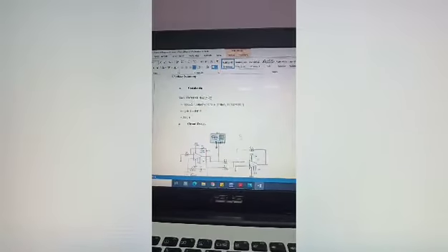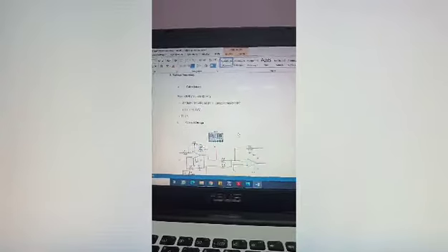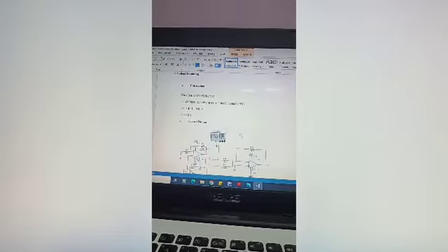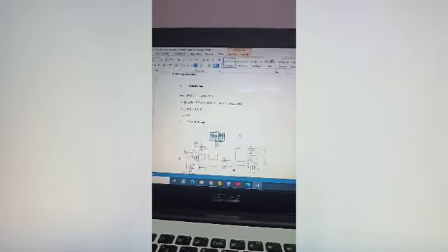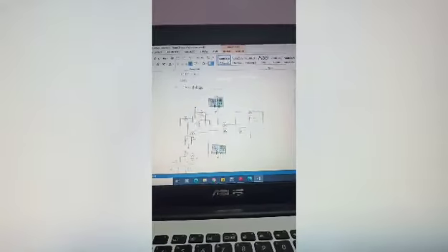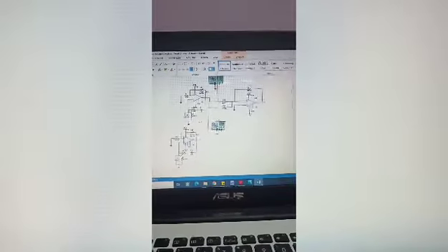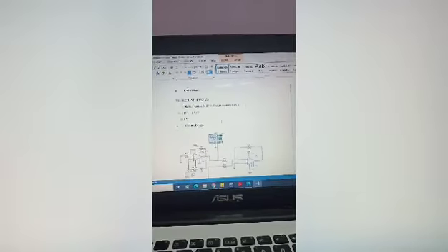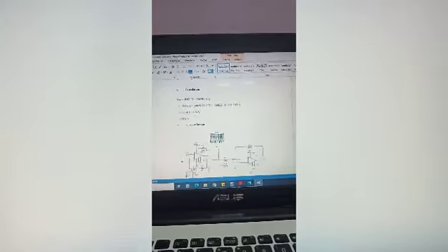Hi, my name is Gayatri Saravanan, matrix number B0818101993. I'm going to explain voltage summing and the active low pass filter. First of all, what is voltage summing? Voltage summing is an op-amp circuit used to combine the voltages present on two or more inputs into a single output voltage. In this case, we use voltage summing to combine the output voltage of oscillator 1 and oscillator 2. Here is the circuit, and we have calculated the output voltage.